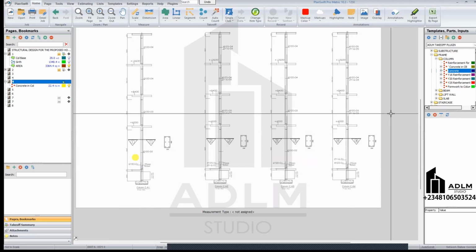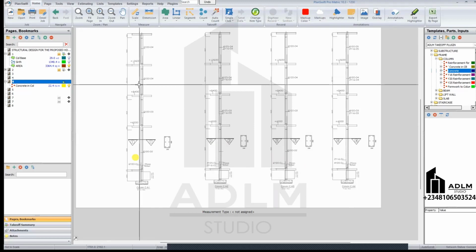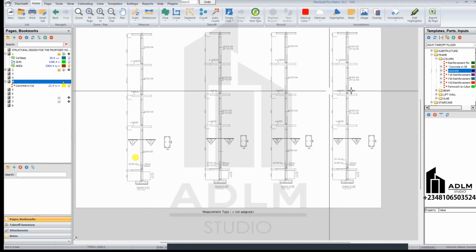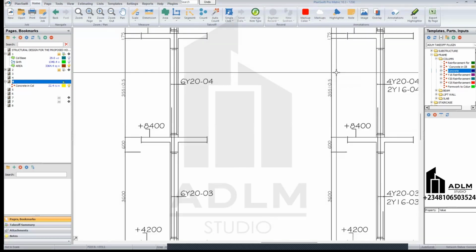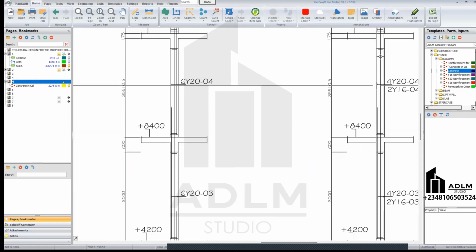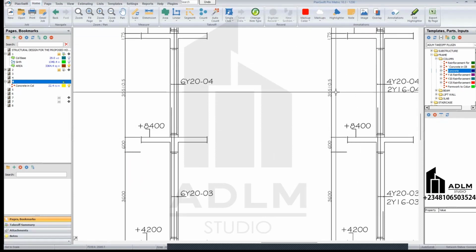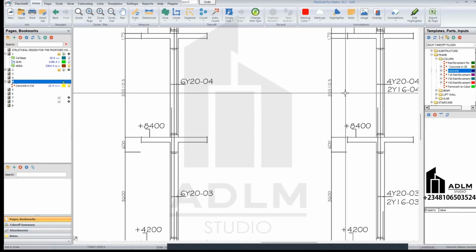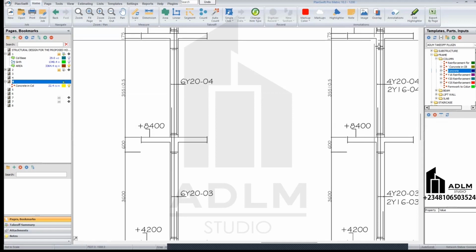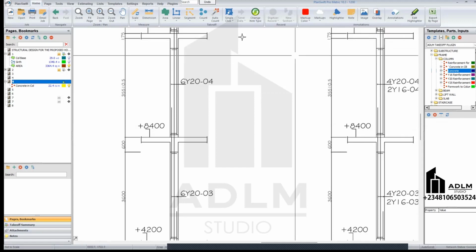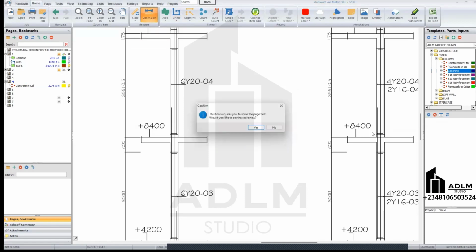Now, once you measure for concrete, let's measure for this third floor here. And that's because it's the same across both. That's the same height of this. But we know from this point to this bottom of slab is 3.55. From this point to the bottom of slab is 3.55. So we have to measure from here down here. So what I'll do is come to my dimension tool.